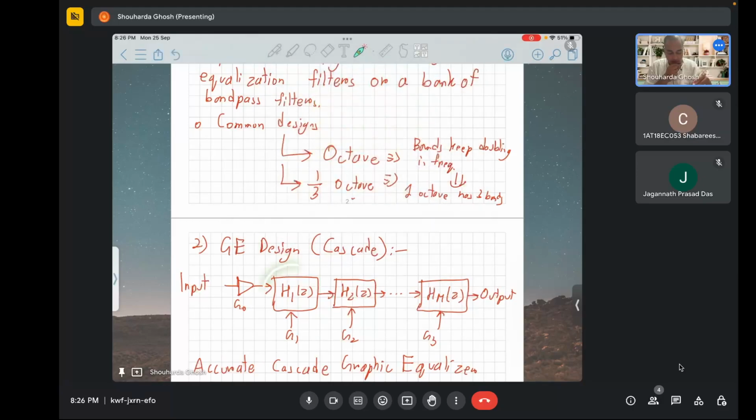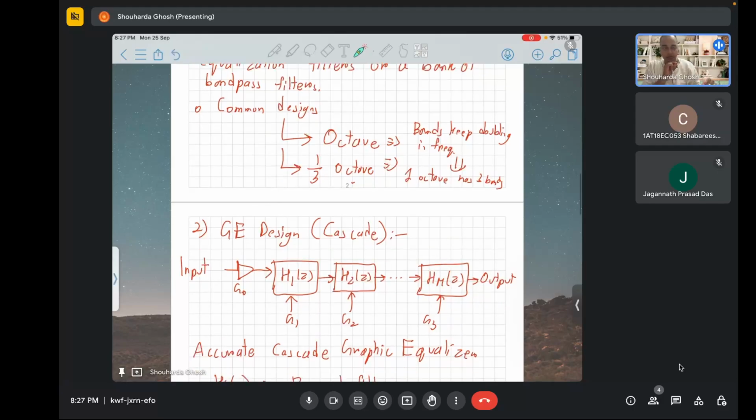where, let's say, this one amplifies your signal by a factor of 2, this one amplifies your signal by a factor of 10, and the next one will be by 20. If you have set the gains in such a manner that it keeps on amplifying all the values, then the corresponding bit widths inside our filter will also keep on increasing. As you keep on going in this direction, you have to use larger and larger bit widths, and that makes our circuit much more area consuming and power consuming, which is not what we want.